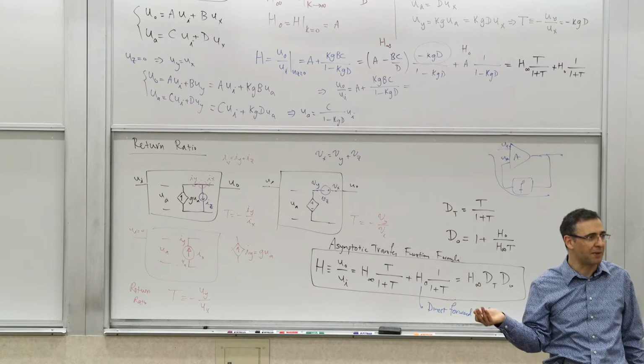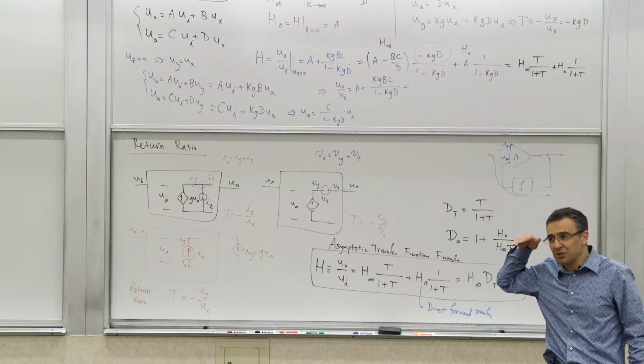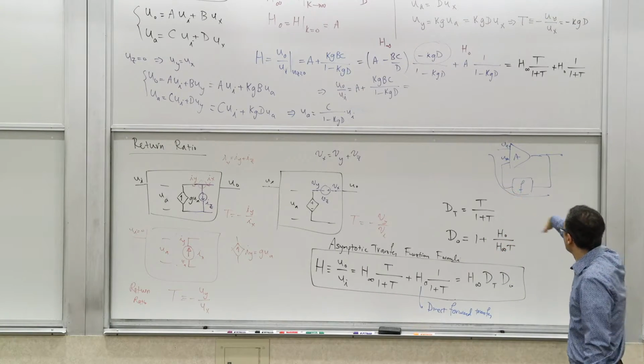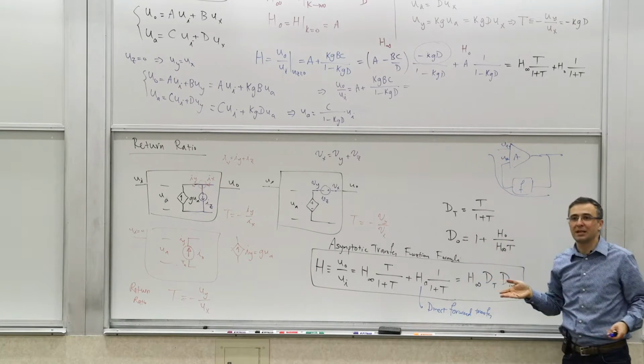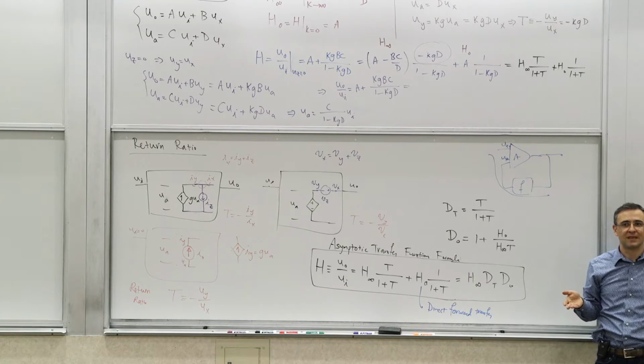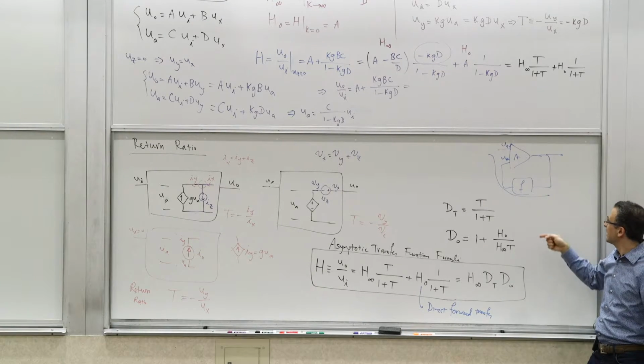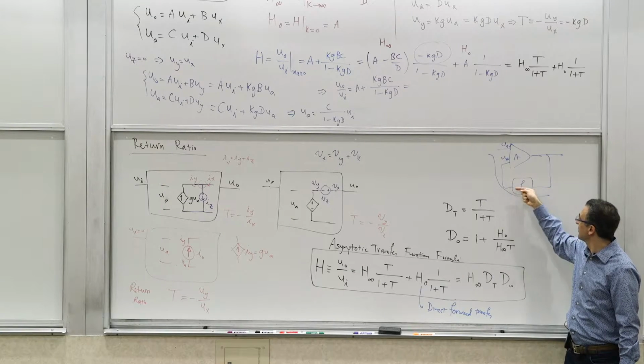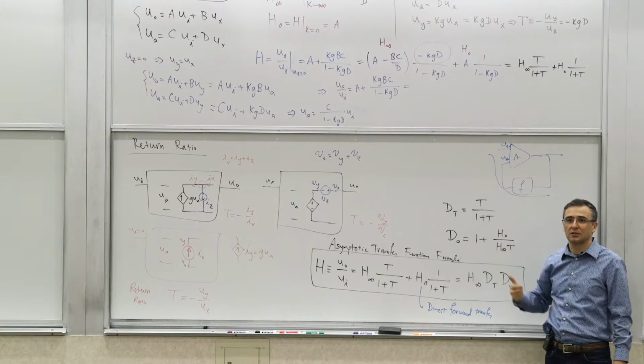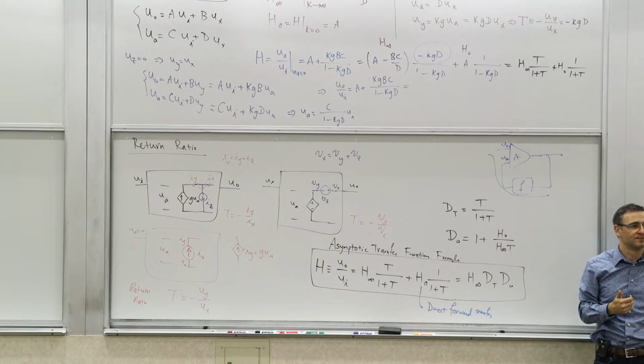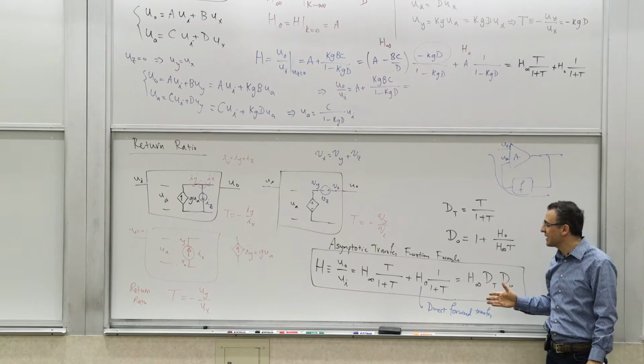It doesn't even have to be the feedback path. It's a measure of how much of the signal actually goes forward just because of this network being there. And these networks are not necessarily unilateral, meaning that they transfer signal from right to left, but they can also transfer signal from left to right. So all of that is taken into account.